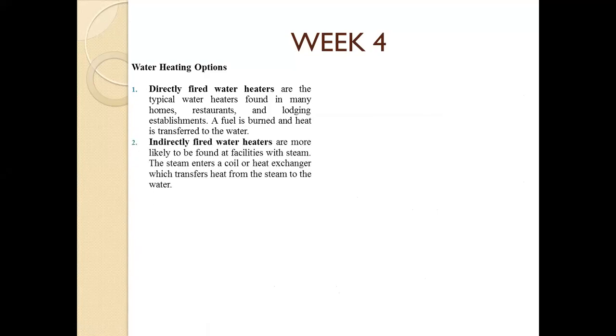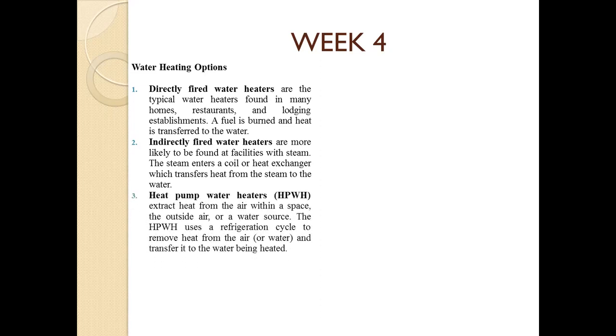Indirect fire water heaters are more likely to be found in facilities with steam. Okay? So ito yung steam. Heat pump water heaters or HPWH extract heat from the air within a space, then the outside air or water source. The HP uses a refrigeration cycle to remove heat from the air or water and transfer it to the water being heated. Solar energy has seen limited use for water heating, primarily in sunny locations.